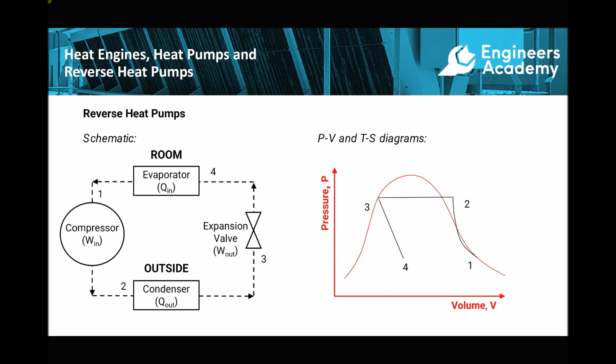So what we're going to see this time is heat energy being removed from the room or drawn out of the room and moved into the working fluid or the refrigerant. Therefore, the temperature of the refrigerant increases, but the temperature of air in the room is going to decrease, which is our desired effect. The refrigerant is heated at constant pressure, so we see pressure remaining constant but volume increasing.